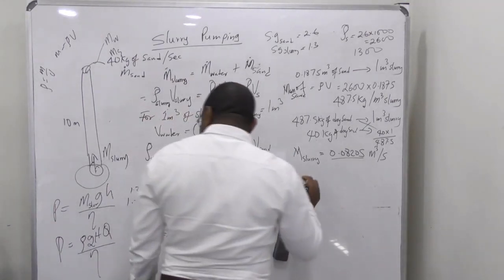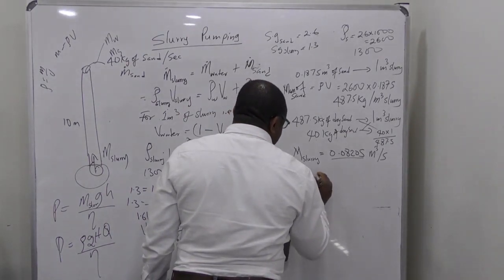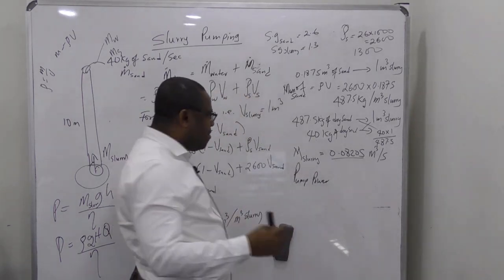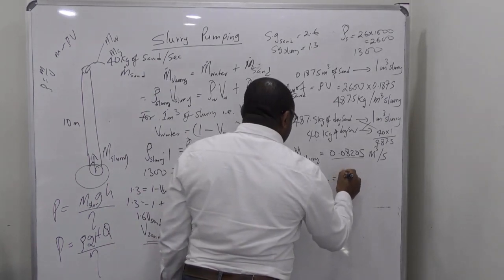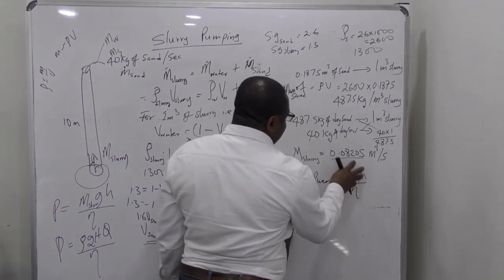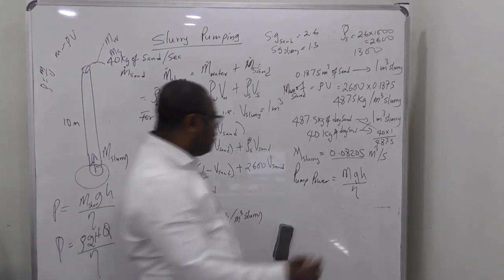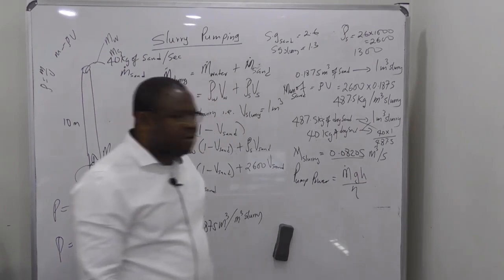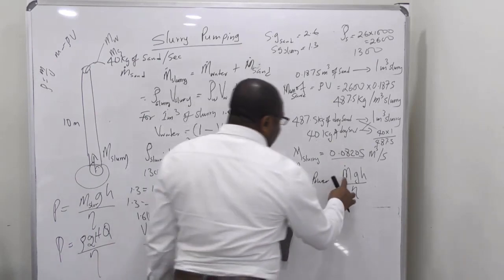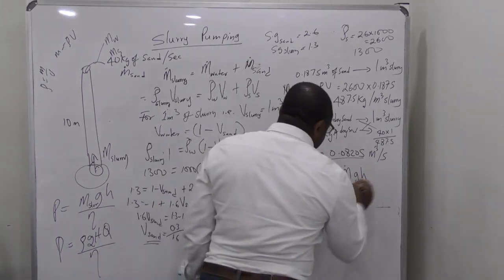Okay, so pump power input, P in. Remember, it's going to be mgh divided by efficiency. Remember this energy that we got there, mgh. Now, if I put it with a dot, the rate with time, we now get our power. This is energy, mgh. Now, with the dot, which is with time, we get power. That's all. So we can just use that.